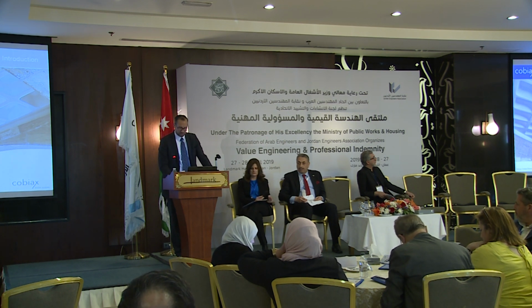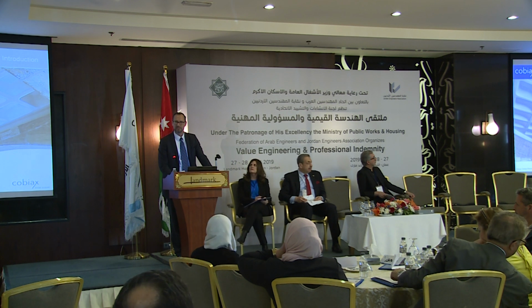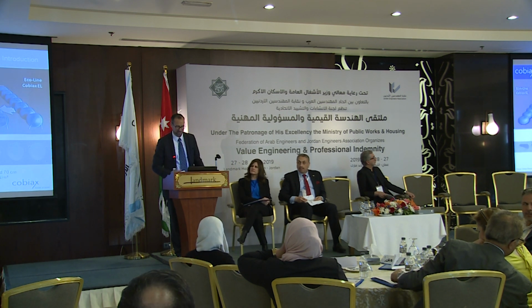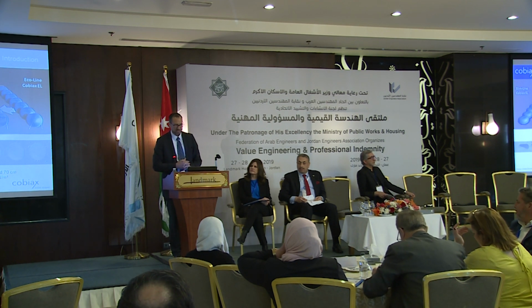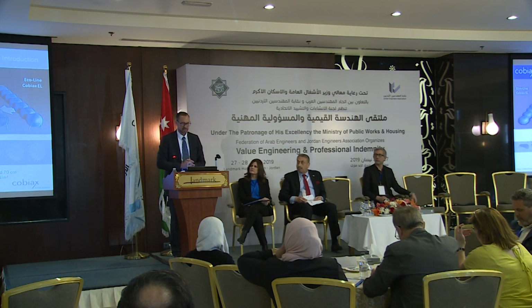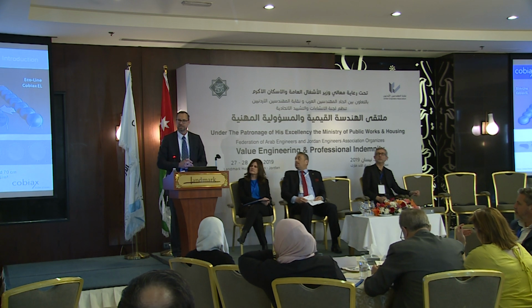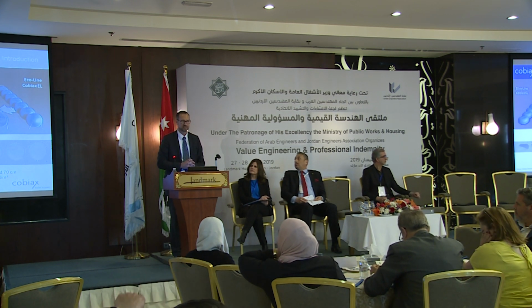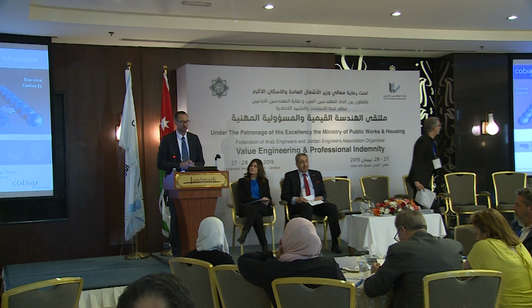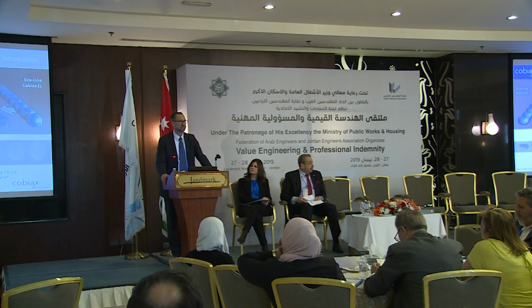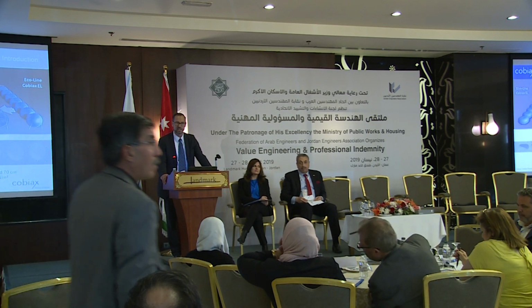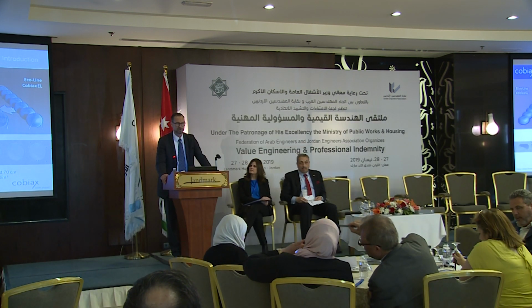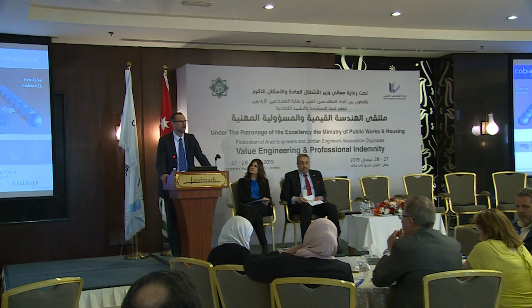But anyhow, we try to do it in a somehow better way, a more intelligent and more modern way. As you see on this slide, we are talking about so-called void former modules, made out of reinforcement cages with integrated void formers, and you place these modules between the reinforcement layers.